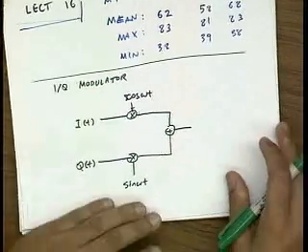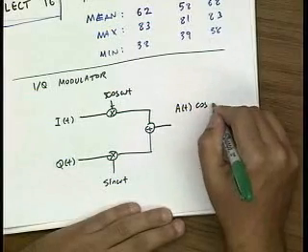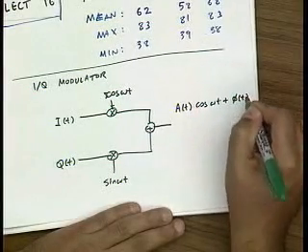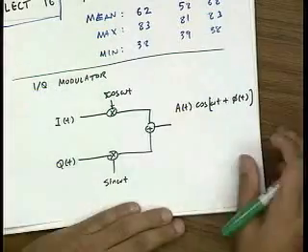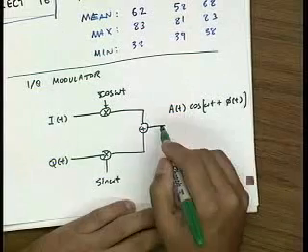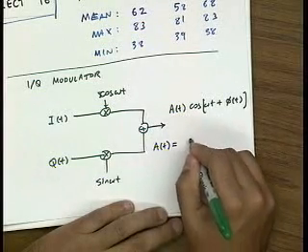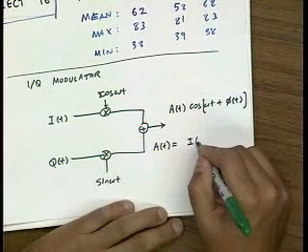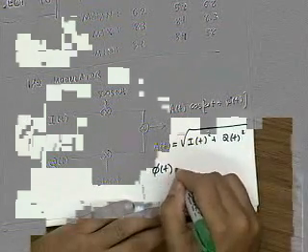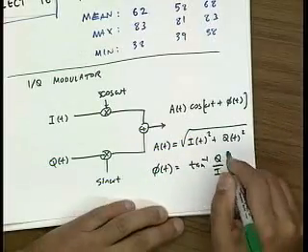We showed last lecture that this sum signal has an amplitude and a phase, which basically allows us to use this one dual mixer configuration to do amplitude modulation and phase modulation. So last lecture we showed that the amplitude of this signal coming out is the square root of I of t squared plus Q of t squared, and the phase of the signal coming out is the inverse tangent of Q over I.